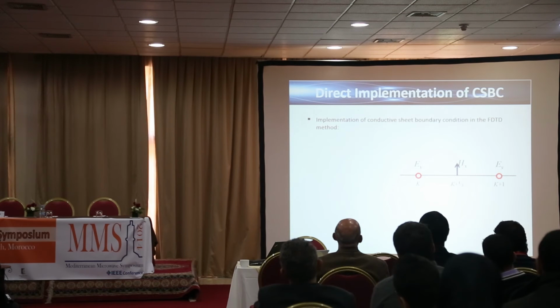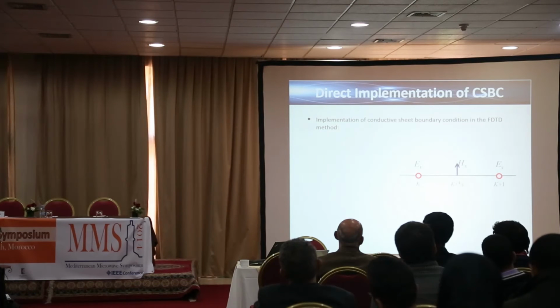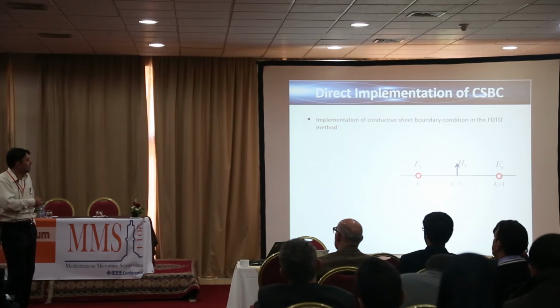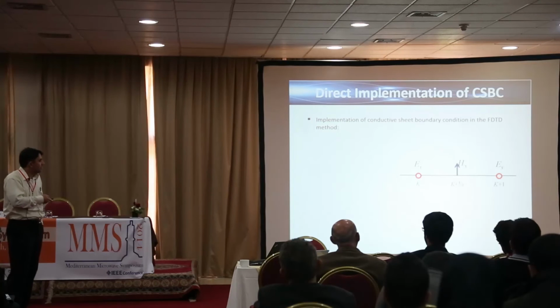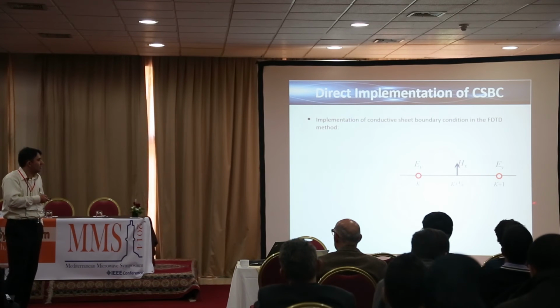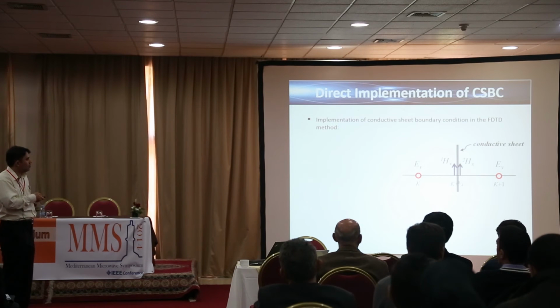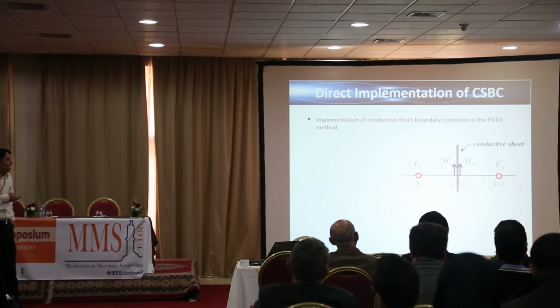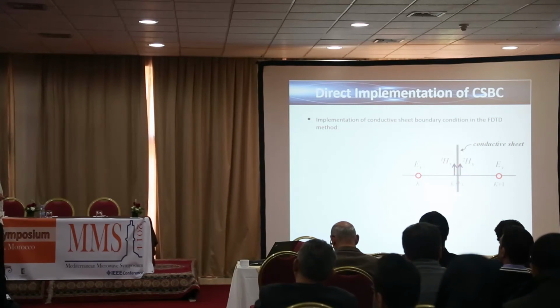We implemented the conductive sheet boundary condition in the finite difference time domain last year. Here you see a one-dimensional finite difference time domain study. And if we put a conductive sheet here, we need to define the magnetic fields at both sides of the sheet.